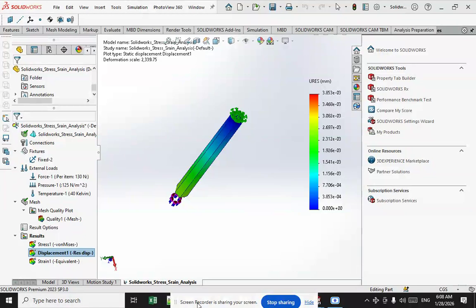In some other cases, for example, elastomers and plastic materials, the change in the cross-sectional area is significant. For the case of material where the volume is conserved, for example, Poisson ratio is equal to 0.5. If the true stress is desired, it must be calculated using the true cross-sectional area instead of the initial cross-sectional area, as sigma_t is equal to 1 plus epsilon_e multiplied by sigma_e, where epsilon_e is the nominal engineering strain and sigma_e is nominal engineering stress.